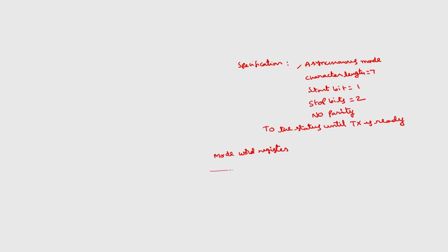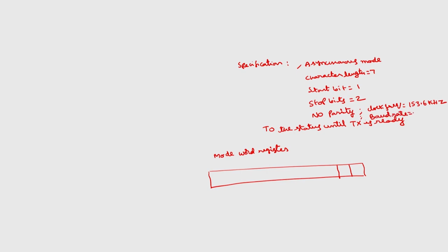So, what will be the mode word register? What are the last 2 bits? And I want to use another specification here, the clock frequency. I want to use 153.6 kilohertz, and another one is baud rate, which is 9600 bits per second.